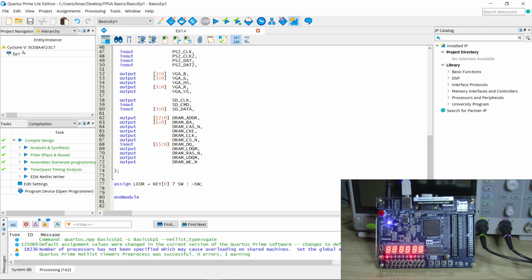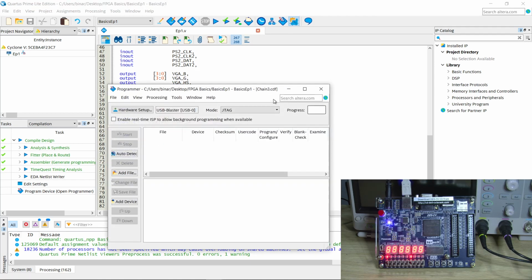That can be really useful for making sure that the computer has understood what you're talking about with the Verilog HDL and that it is actually going through and implementing it correctly. You can actually go through and have a look at the circuit diagram and go, has it wired things up the way that I thought I described it? Because it might be that you've missed something like an input or an output and it's gone, okay, that section of your code is not relevant, therefore I don't need to create the circuitry for that part. It's something that can be really useful for trying to find bugs and things like that with the Verilog code.